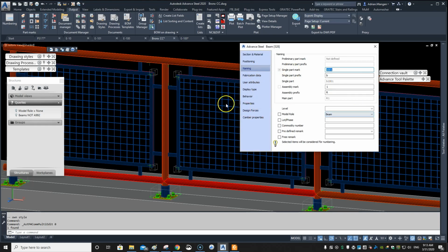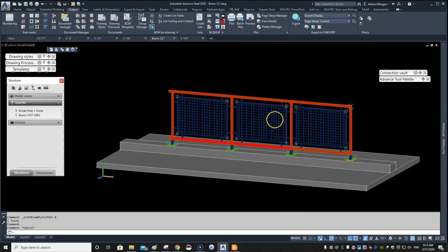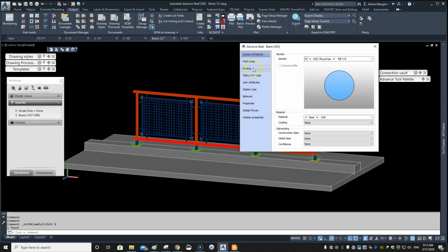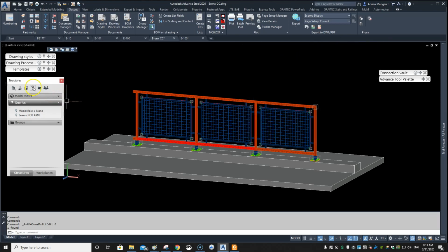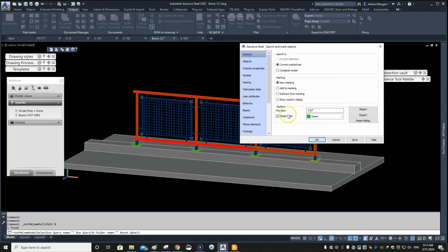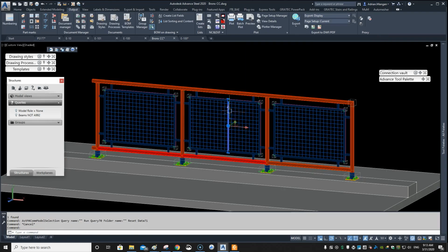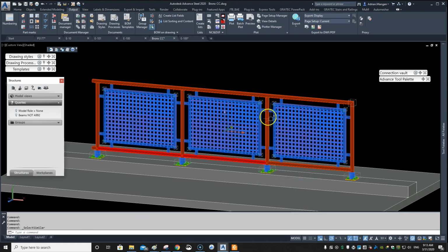Naming. See, these are all named as beams. I apologize. So what I haven't done is I haven't set up this. I need to change the bars because everything is controlled off the model roll. So what we'll do is we'll set up a query, and because sometimes you can just select an element and do select similar, but it's going to pick anything that's like a beam there.